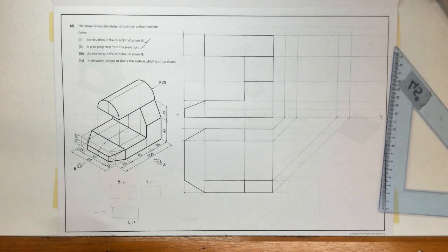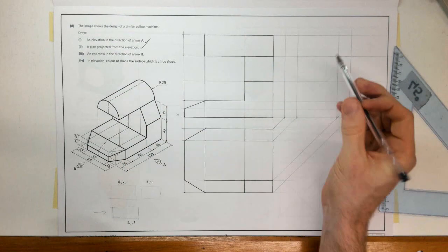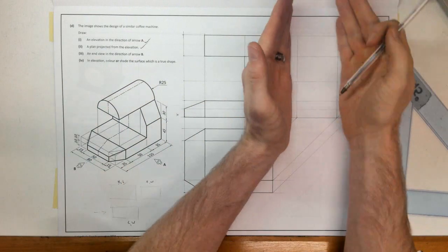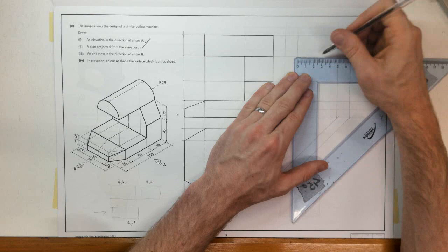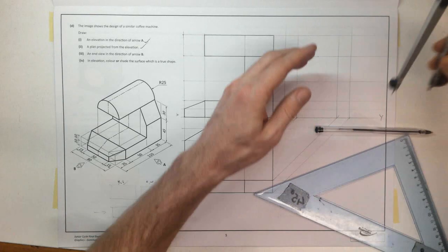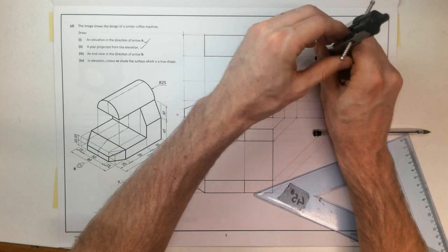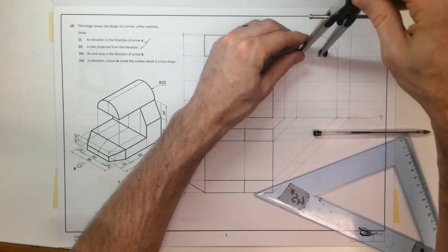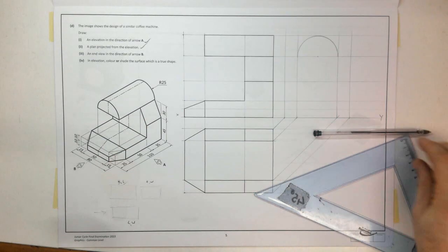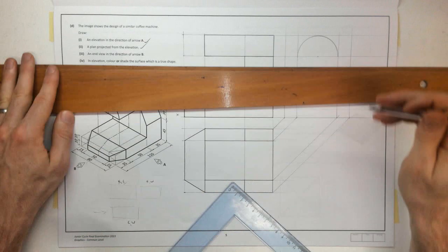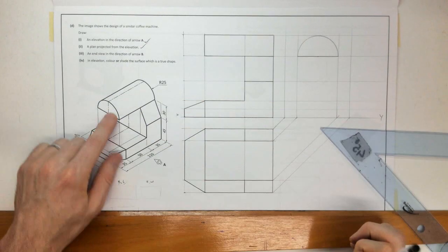Okay, I'm going to start with the cylinder at the top, which is radius 25. So that's fitting into that space 50, so it's fitting here. So I'm going to measure across my 25 to the center and set my radius to 25. There we have the cylinder, or the semi-cylinder. Okay, and that's an edge then across the base of it. So that's what we see there.